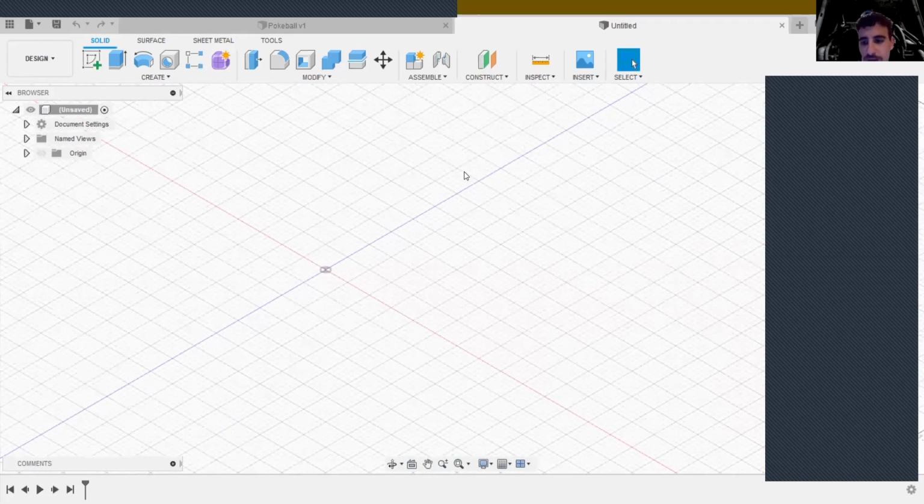Since we have a few first timers here, there's certain processes in 3D modeling. So the most basic one is a sketch, where you start drawing a two-dimensional sketch, and we'll be doing a function or a feature on that sketch to make it three-dimensional. And when we do our sketch, we always have to sketch on something or in a reference to something. So our first primary references are the 3 planes.